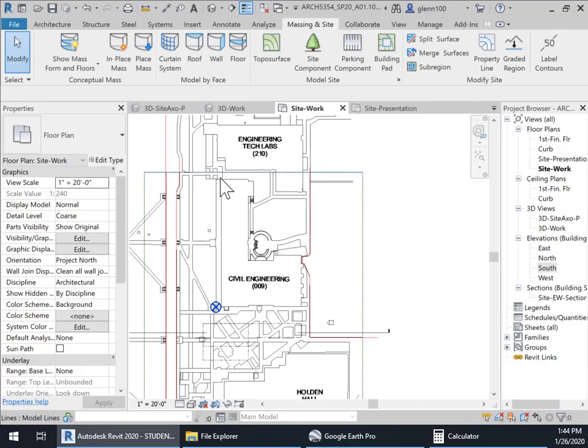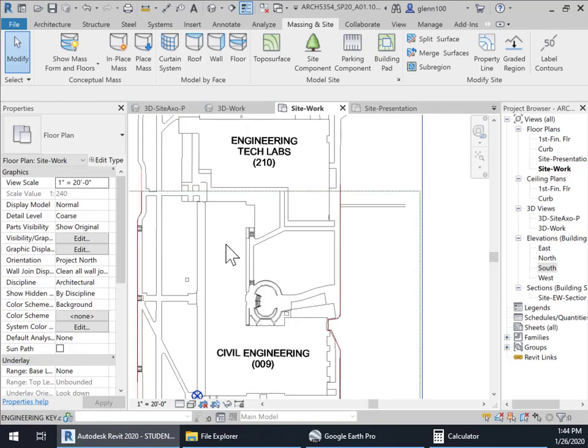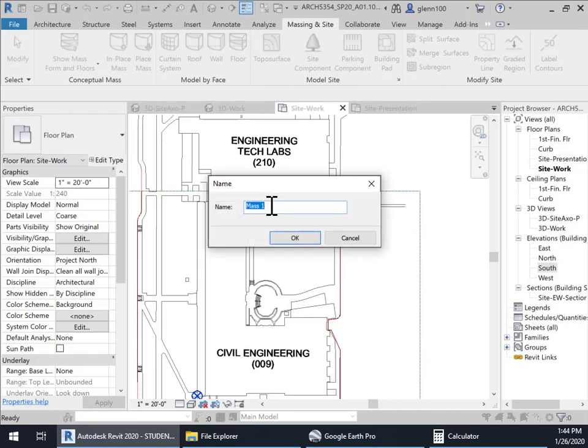And of course, this is all that sloped tile. So I'm just going to throw all these model masses in really quick and show you. So we're going to go in-place mass. In-place masses start out as a vertical extrusion, versus components, where you don't have the options to do lofts and all that kind of stuff. So if you need those kinds of abilities in this mass, you might want to try out using a component rather than a building mass.